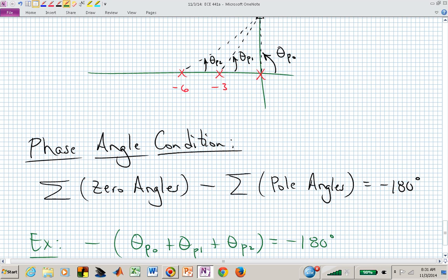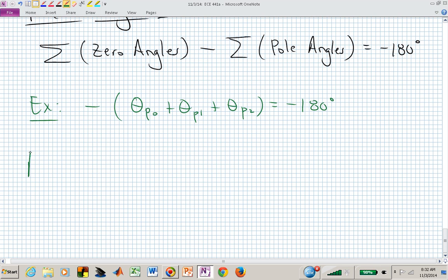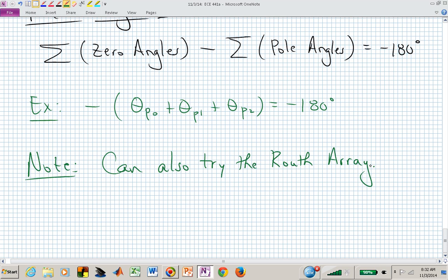This would do it. Here we're sort of guessing where that box is going to be, but it's going to be close to where those asymptotes are crossing. So you could come down a little bit and calculate your phase from all three of those angles, or from all three of those poles. Is that clear? But let's now do it another way. Let's use the Routh array. Since we have these techniques, let's now start connecting those.